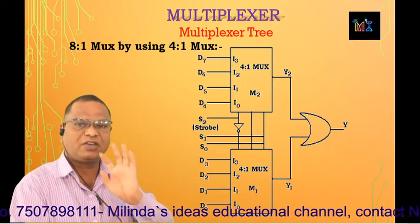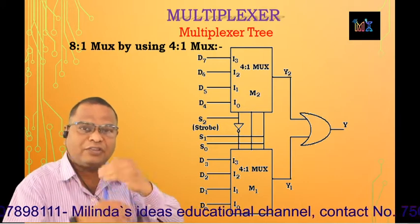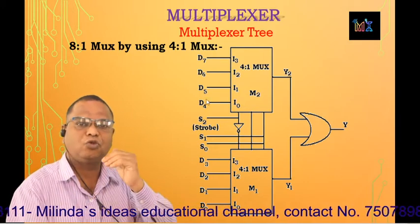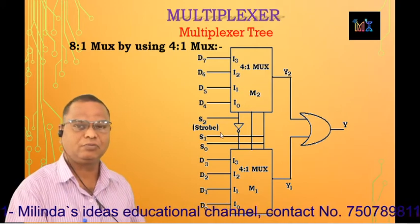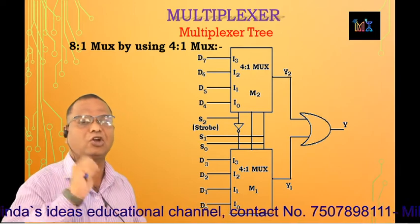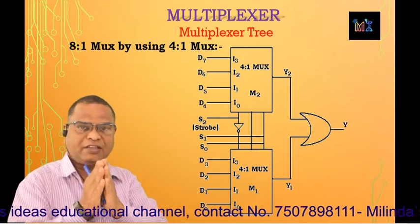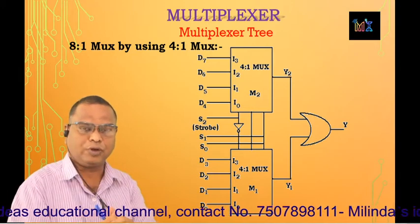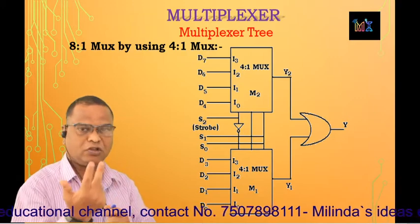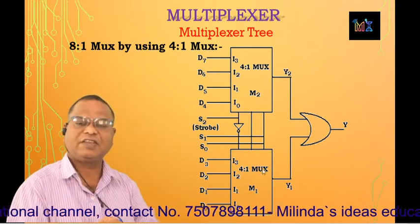When 2 mux are connected, we are going to select one of the mux, and for that purpose there is a provision known as a strobe or an enable. So in this case, the strobe input is used as a control input. The third control input, that is S2, is connected to the strobe input. How is it connected to the strobe input of the particular mux? As there are 2 mux, the lower mux is considered as M1, the upper mux is considered as M2.